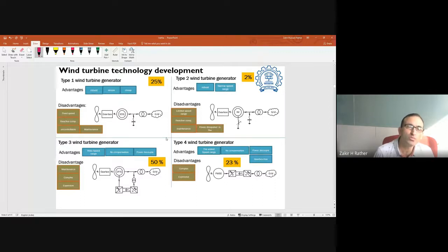And these conventional sources have been providing inertia in the system. The beauty of these conventional generators is that they have an inherent capability to support the grid, be it frequency or voltage. When it comes to frequency stability, for those familiar with synchronous machine operation, the rotor poles of the machine are locked with the rotating magnetic field of the stator, or in other words, the rotor is locked to the speed of the grid frequency.